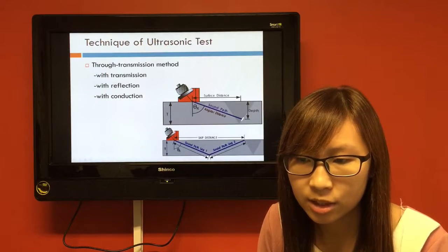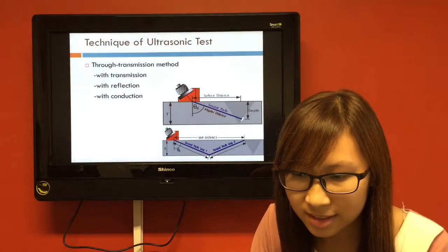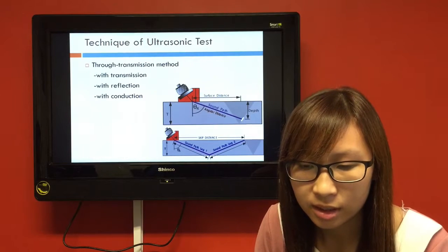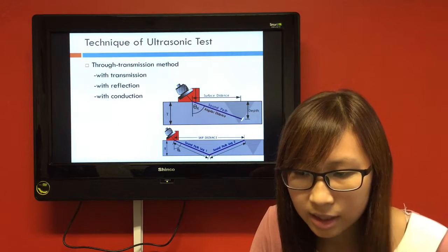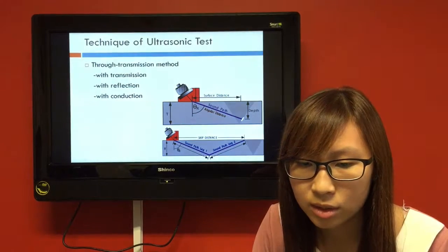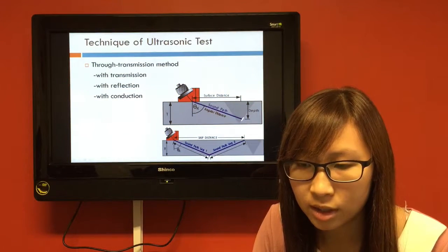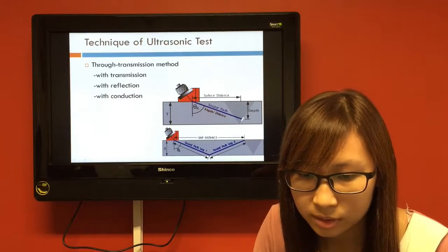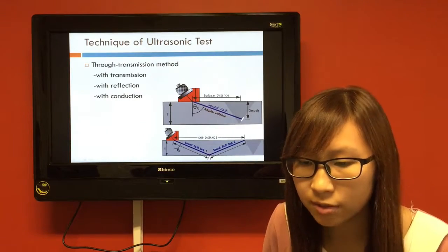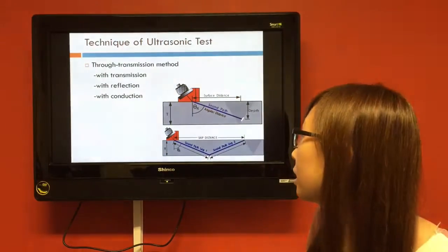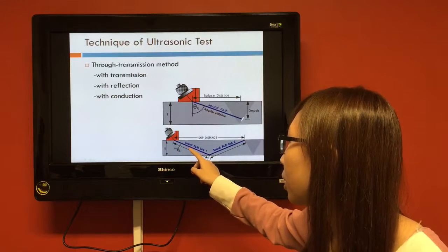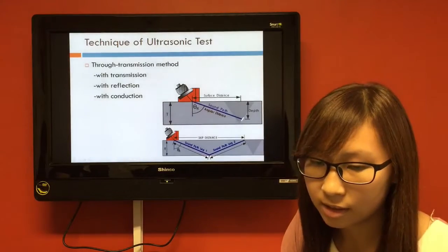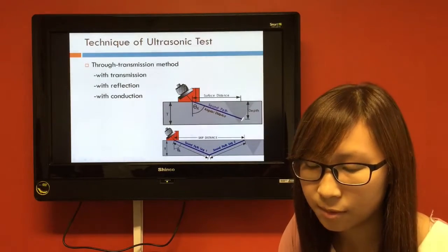In most applications, the transducer is placed over the surface of a stainless steel block and you can see return echoes as they appear on the oscilloscope. The geometry of the sample is in this graph. The sound path will refract to detect the defects.